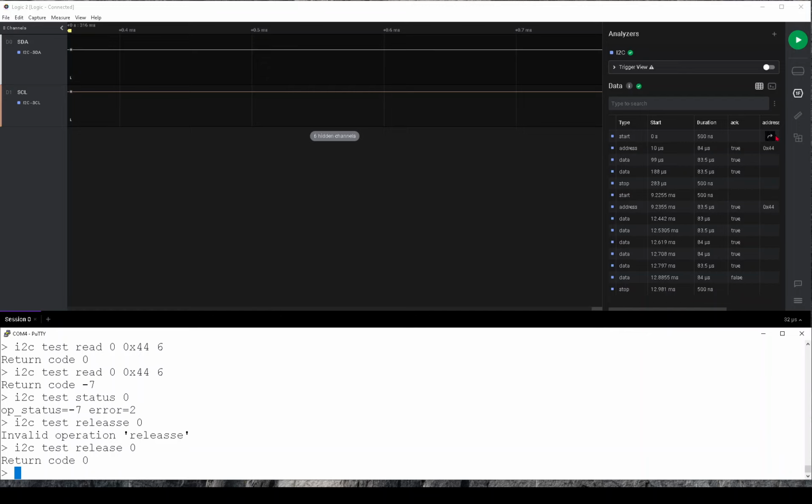We did a successful measurement. Now, you could argue that, well, tough luck. You didn't issue a one-shot measurement command to that sensor chip, so when you tried to read it, it did what it did, and it's your fault. And okay, I sort of accept that, but it's still not very nice.